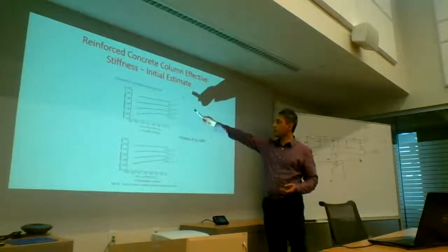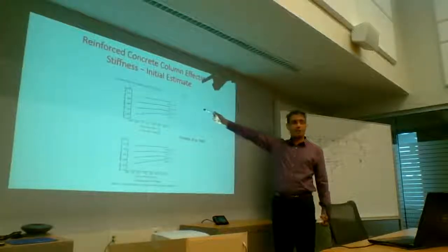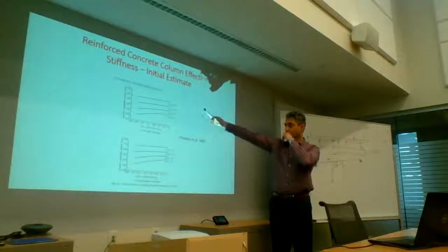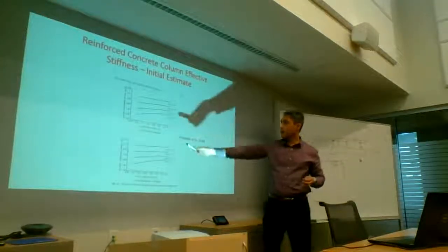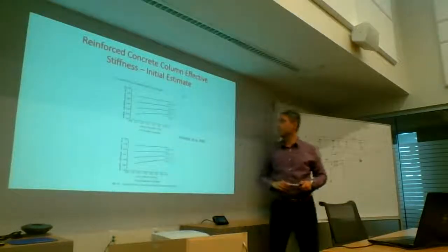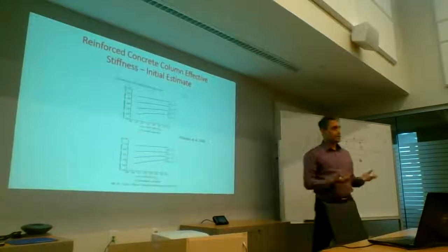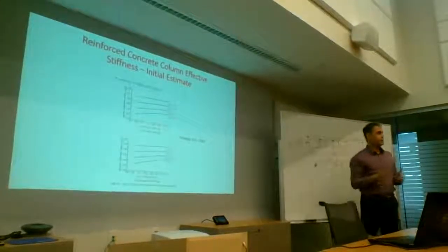And you can see the range. If you have 4% rebar, which if you stuff that much in there, the contractor is not going to be happy. And your axial load ratios, you may get up to 0.7, and you may get as low as about 0.3. That's sort of the range we're talking about. I will tell you that good design for bridge columns is 1 to 2%.